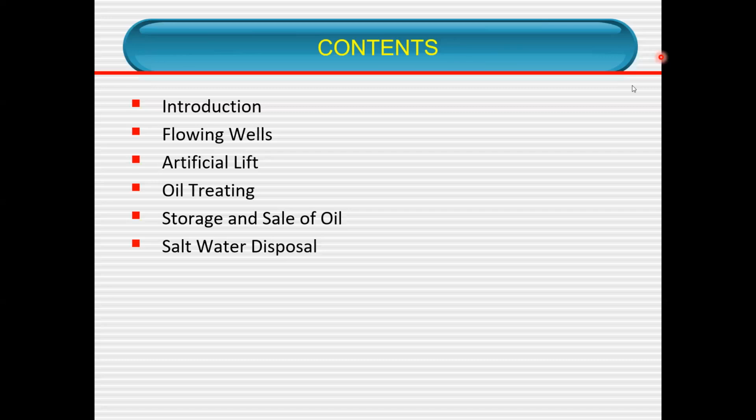When you're talking about wax deposit in my first or second year of working, since heat can melt the wax, why are we worried about all these chemicals? It's not that straightforward, because for the application, how are you going to deploy this heat into that particular location? That is going to be a very big challenge. And most of the time, heat is going to be uneconomical. So you have to find ways to resolve these issues, not only in terms of heat, but chemicals and other mechanical means.